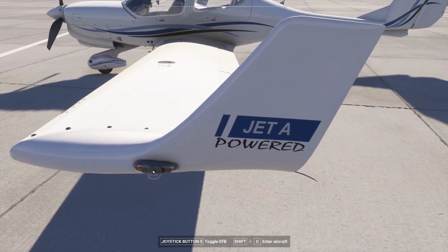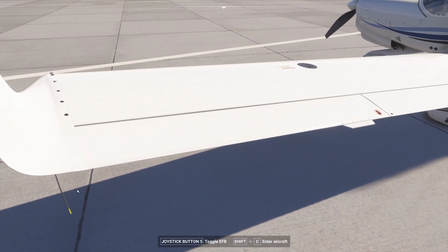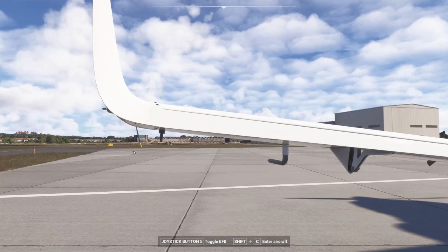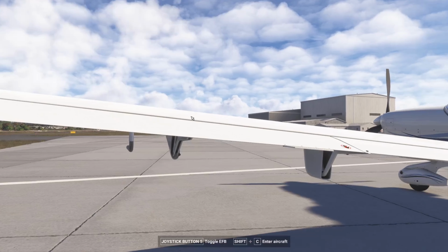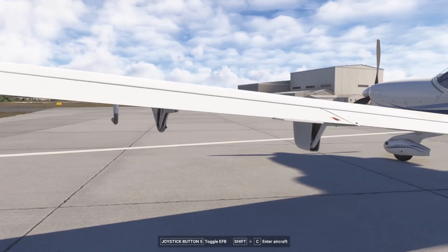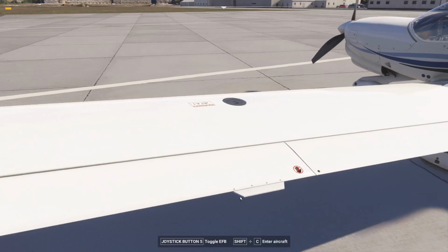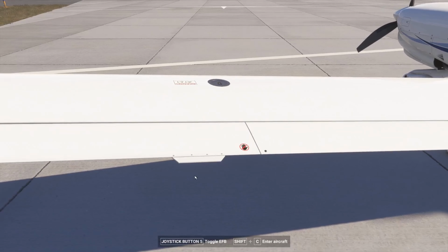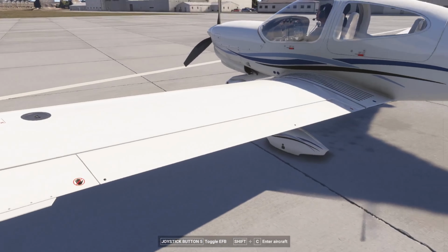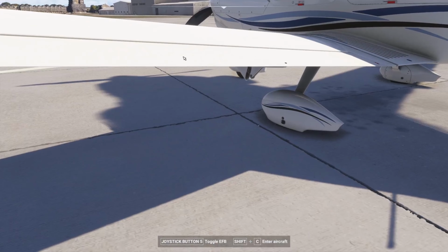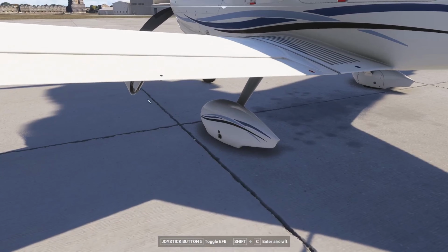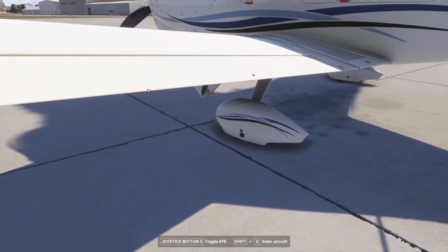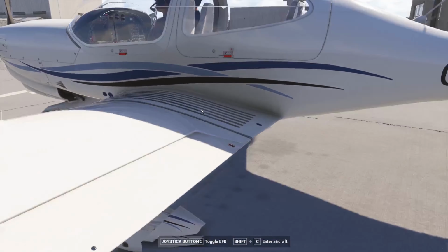We've got our navigation light and strobe lights on the edge of the wing. We've got static wicks on the edge of the wing, so we need to make sure they're attached before flight. And we've got our ailerons here on the edge of the wing with a trim tab here, so you don't have an aileron trim in the DA40, you just have a trim tab, as you probably saw in the PowerPoint. You've got your flaps operating here, so they are operated by a push rod system.